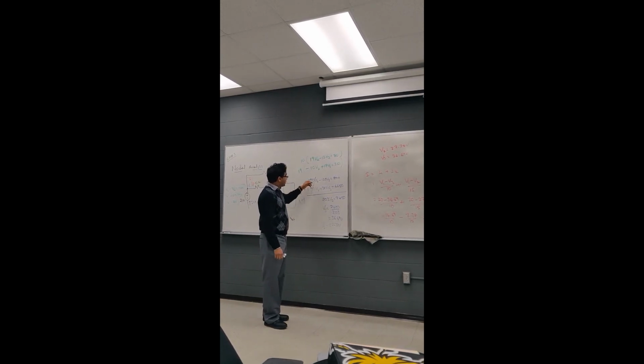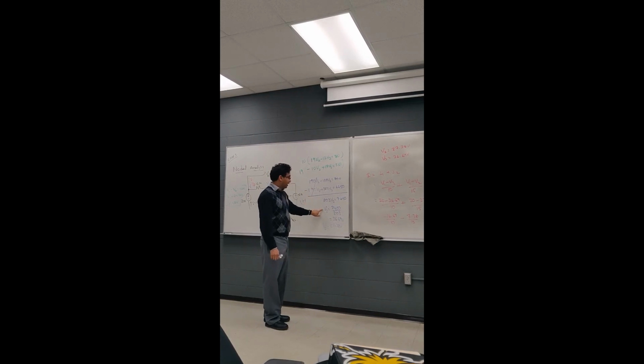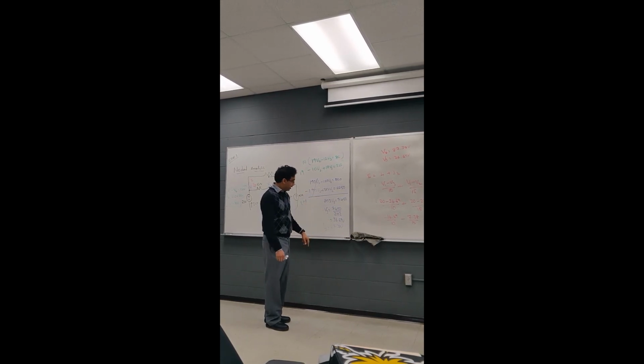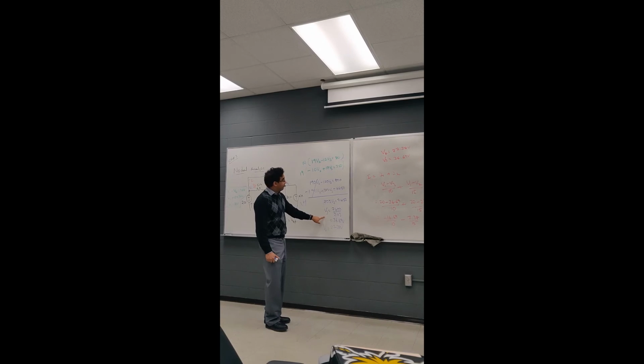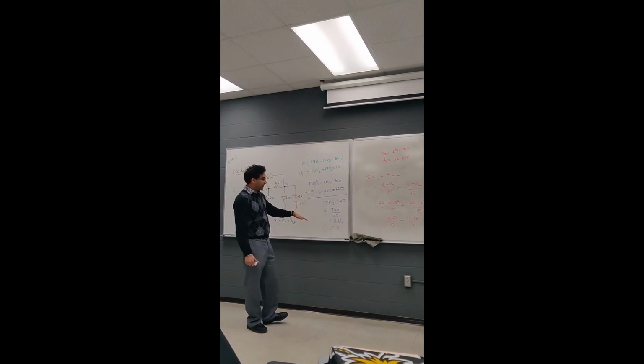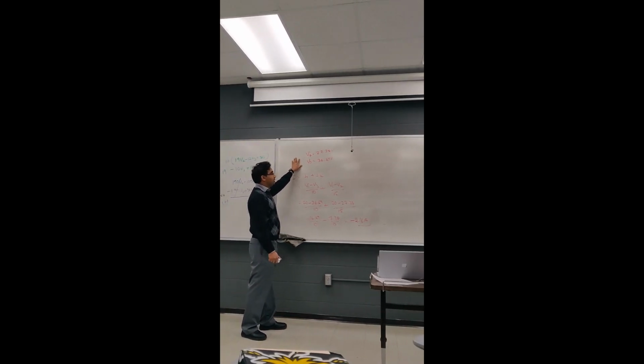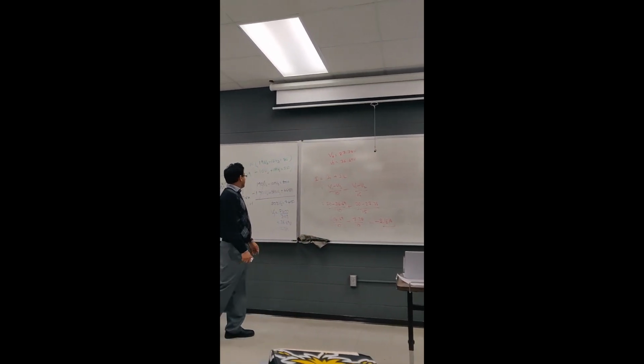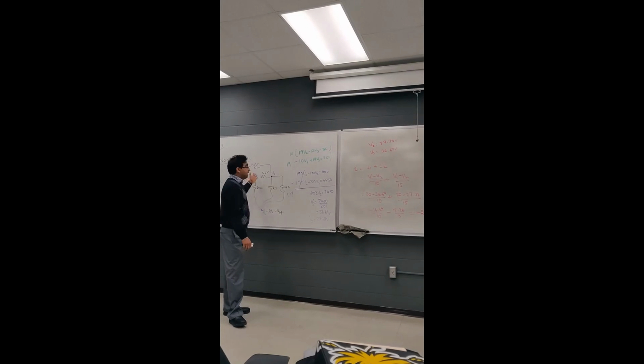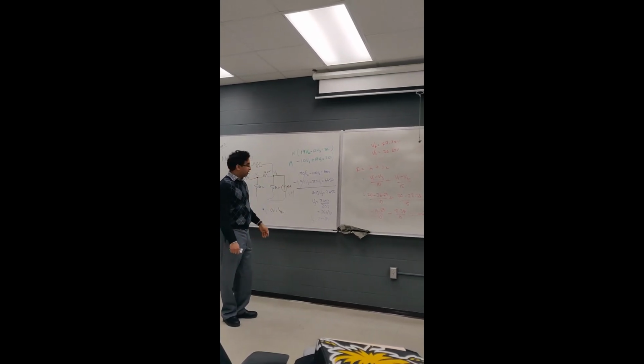So I cancelled V2 and ended up finding V3 equal to 36.69 volts, and substituted the V3 value in one of those 2 equations to find V2. So I end up with V2 equal to 27.38, V3 equal to 36.69. Now I know each and every node voltage in that circuit.